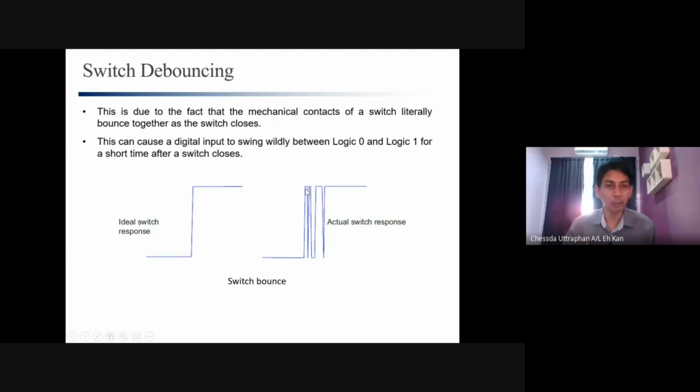It looks like you pressed many times, although you pressed only 1 time. So this one is 1 going down, 2 going down, 3 going down, 4, although you pressed 1 time, because of this bouncing signal, your microcontroller will give you 4.